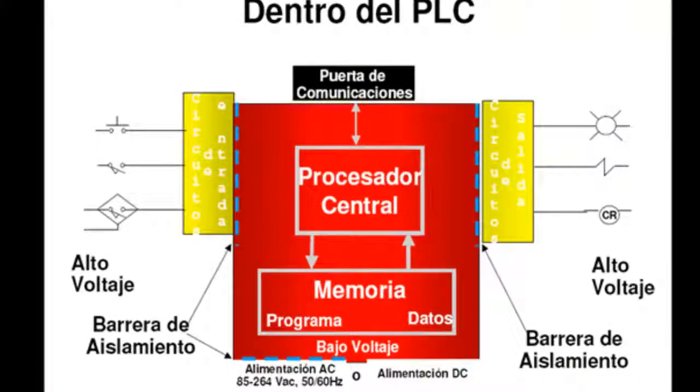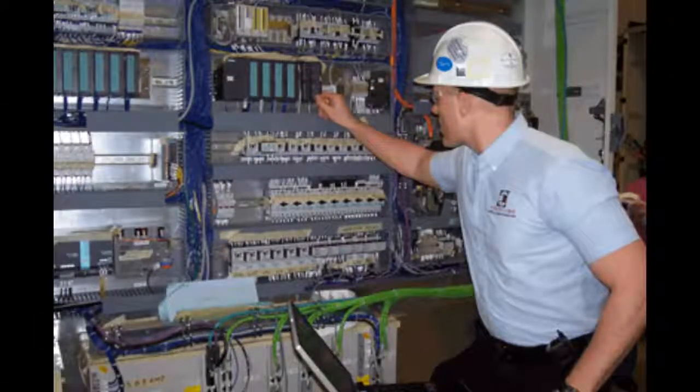IEC 61131-4, User guidelines. PLCs, their application programs, and their associated peripherals are considered as components of a control system. PLC users should take note that this standard does not deal with the automated system of which the PLC system is only one component. However, when applying this user guideline, an overall system architecture evaluation is recommended. An objective of this user guideline is to facilitate communication between the PLC user and PLC supplier according to the specifications.